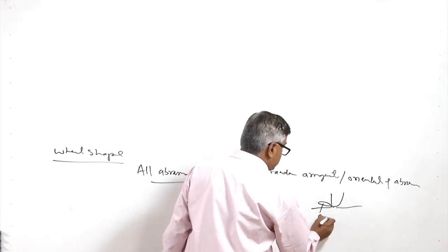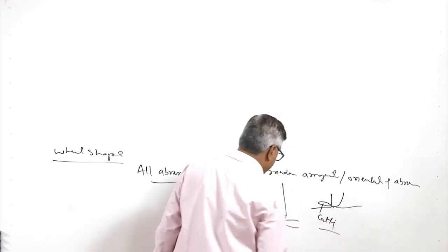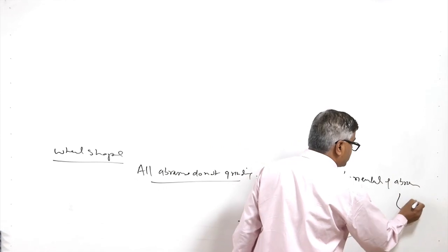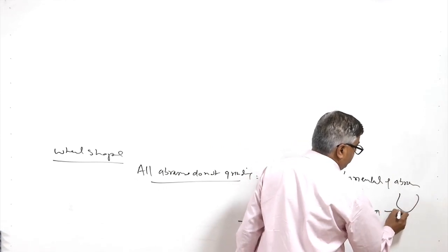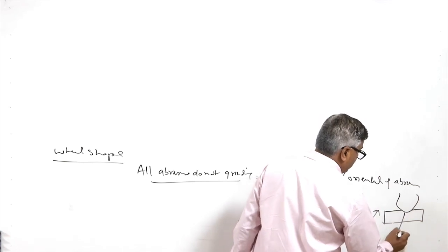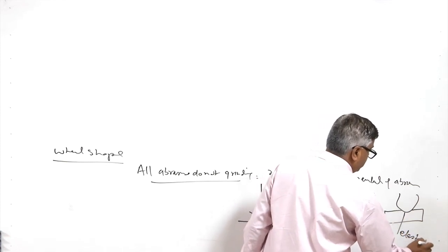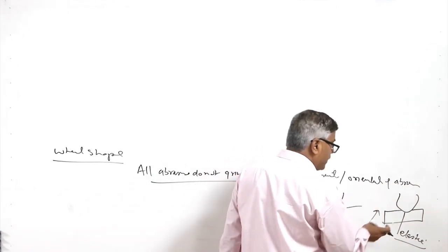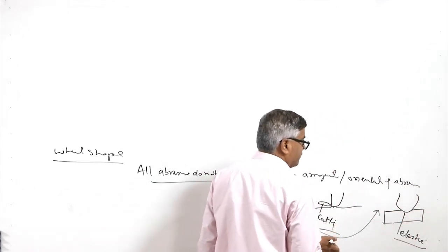So, cutting is being performed in this case. For the second case, the abrasive is just penetrating but not cutting. So, this will lead to the elastic deformation of the material, not the plastic deformation, and even if there is plastic deformation, shearing is not facilitated.